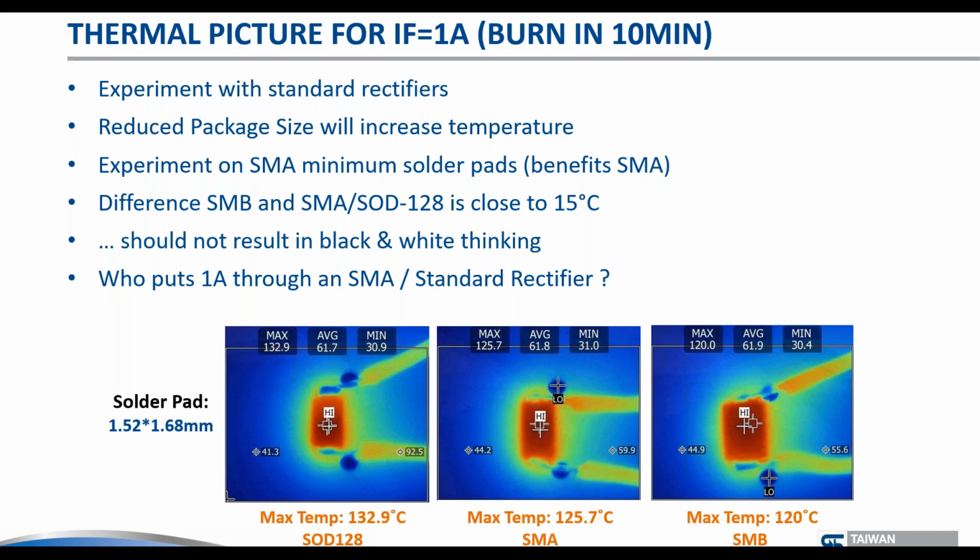If you look here, you see that the SMA and SOD128 have fairly similar performance on their recommended solder pads. SOD128 might be even a little bit better, but then of course you increase the size. And you're getting a difference of, let's say, around 15 degrees C.